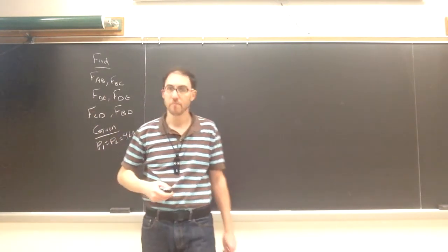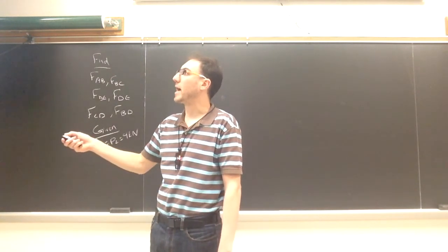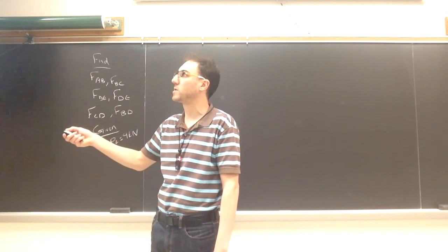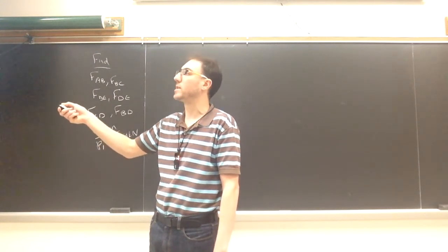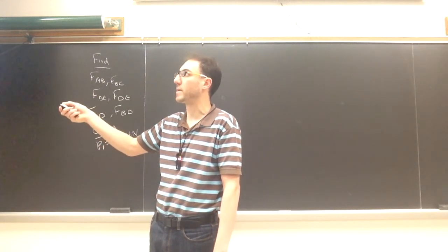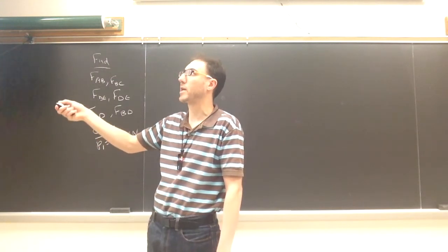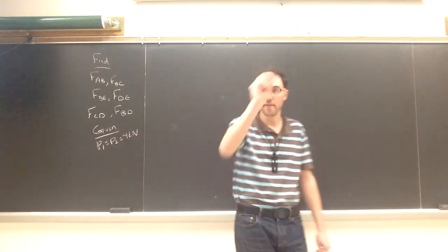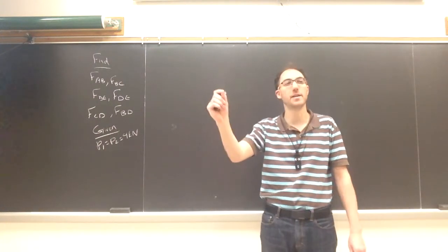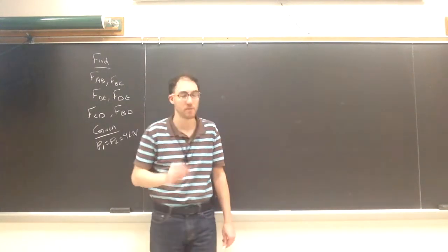If P1 wasn't there, BD would still not be a force member then? If P1 were not here, BD would be zero force from the viewpoint of D. Okay. If BD were zero force, then looking at B, EB would also be zero force, because BE would be the only thing with a component orthogonal to AC. Gotcha. So that's where you can cascade it down. If you could identify one, it might reveal other ones as two force members, or zero force.